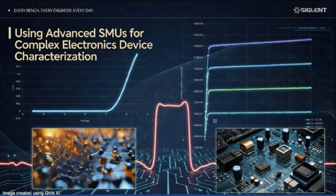So also, we didn't really talk much about fixturing, however you need to make that device measurement, right? Making sure that you've eliminated environmental impacts, while also hopefully not causing a lot of ground loop type issues, is important. So that combination, I think, is where you see a lot of those measurements being made, and where they get kind of tricky. But using these techniques, a combination of the cable techniques and some of these differential offset measurements to try to get rid of and tweak out those offset values to get the most out of your measurements, is I think where the magic is.